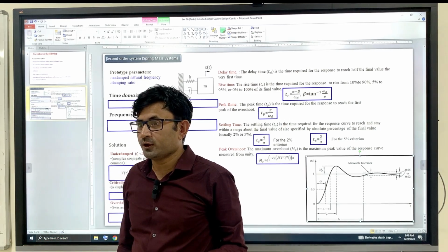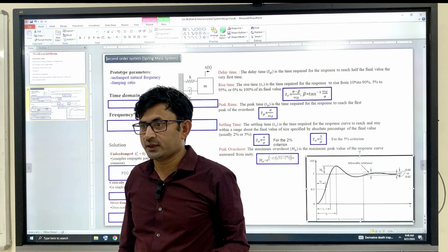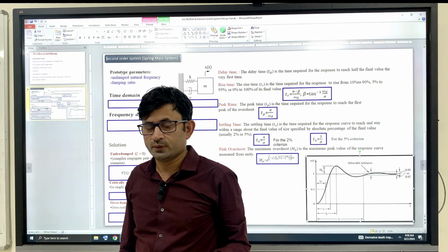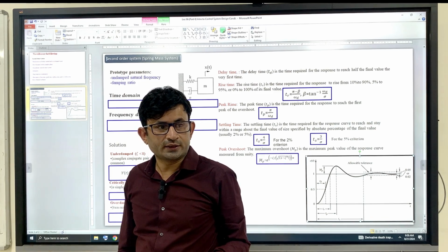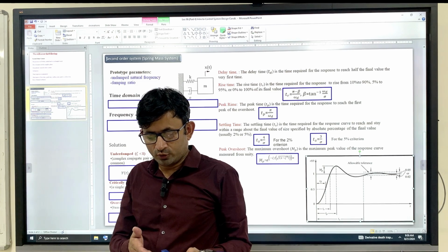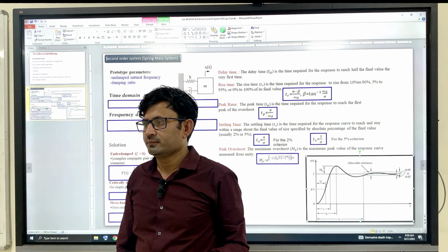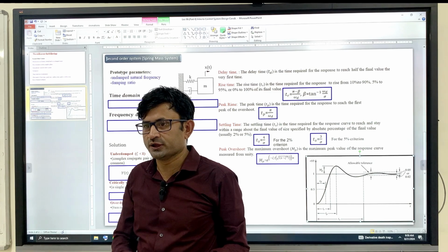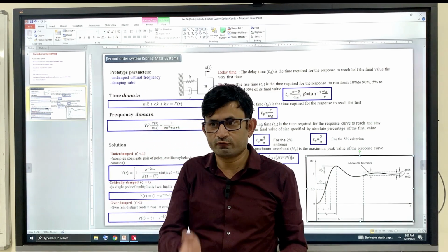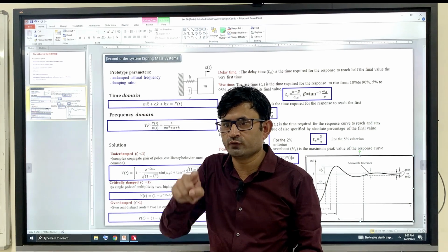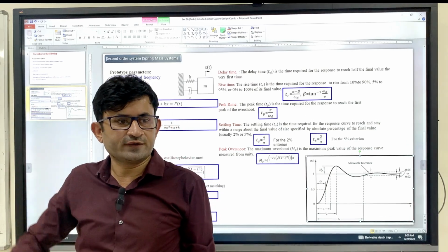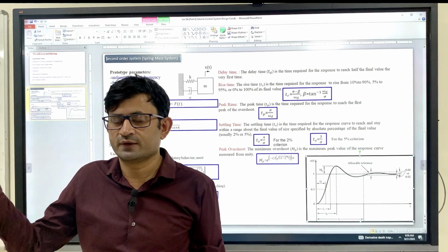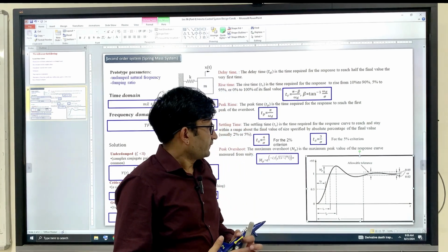But the controller is a math block. So if you do not provide the proper algorithm, then it may say, okay, deflect 30 degrees. Can you deflect 30 degrees or 360 degrees? Meaningless, right? So you have to limit. That is why you have to limit the saturation, so that beyond this, even if it is commanding, you never deflect that much. So that is the part of the integral.